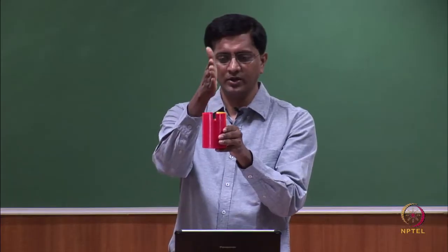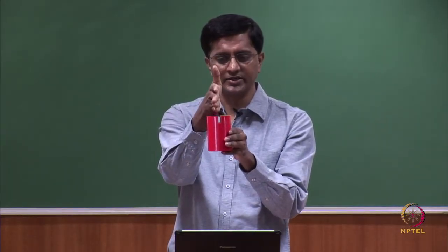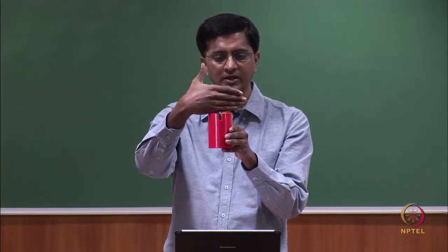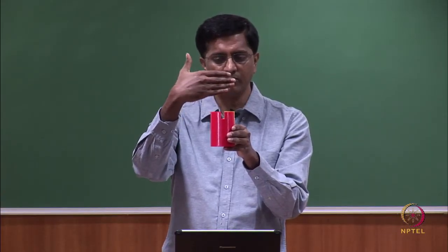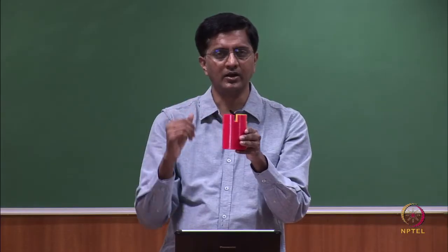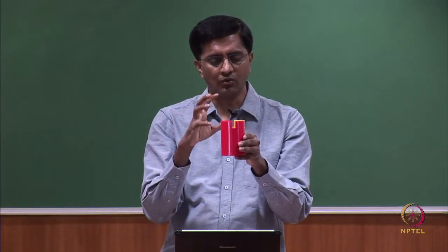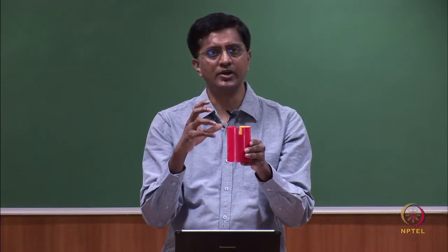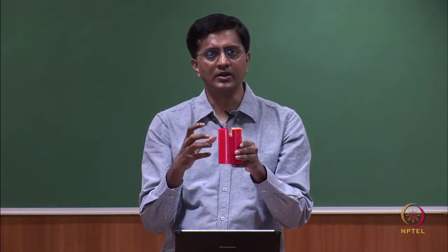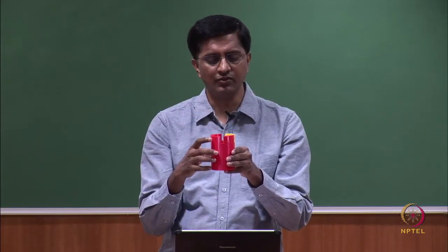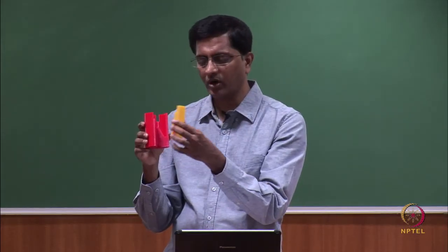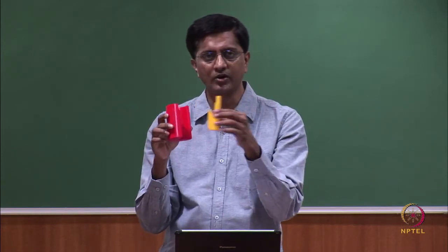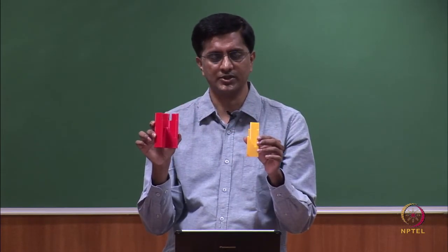For example, if I take a cut plane in this direction, the left and the right are identical. Similarly, if I take a section in this direction, both the front and the rear are identical. So, we have a symmetry in this, and once we have symmetry, we can use another practice called the half section, where we only remove a quarter of the piece. As you can see, I removed a quarter of the piece from the full object.